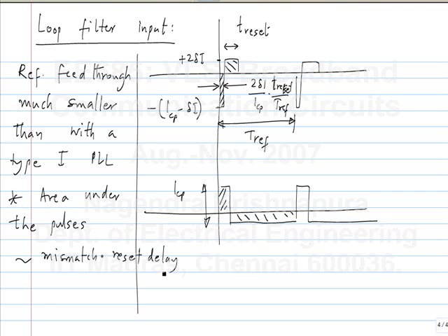That is what the jitter of the VCO is, that's the phase noise of the VCO. Okay. So, the VCO edges may not be uniform because of imperfections in the VCO, but the counter you can expect to count n edges. Now, in reality the counter will also have its own noise. So, let us say the first edge comes at time 0 and the next edge at the output of the divider will not come exactly at the nth edge. It will come slightly before or after it because of noise, but that noise is usually very small compared to the corresponding edge noise of the VCO.